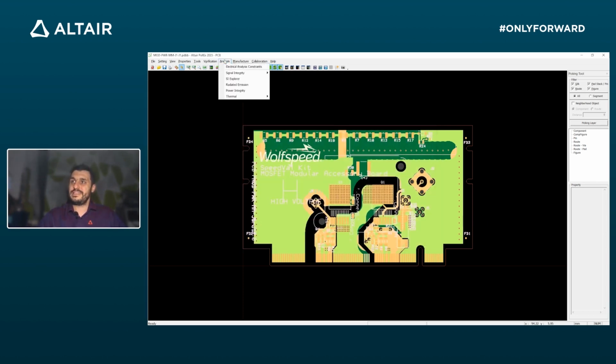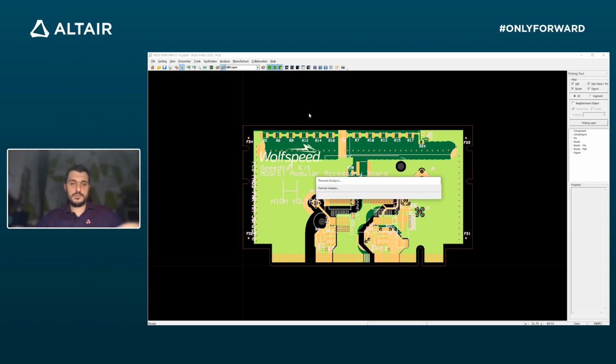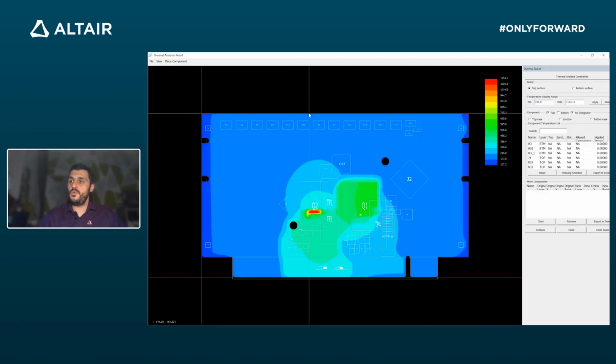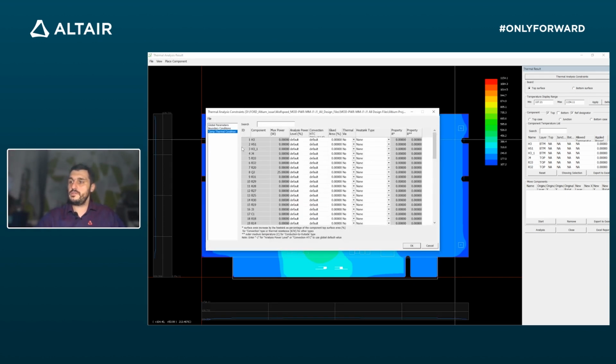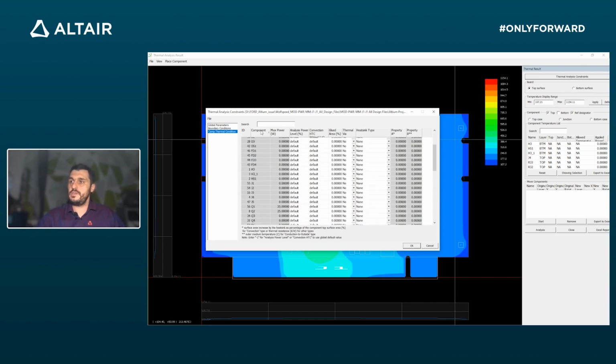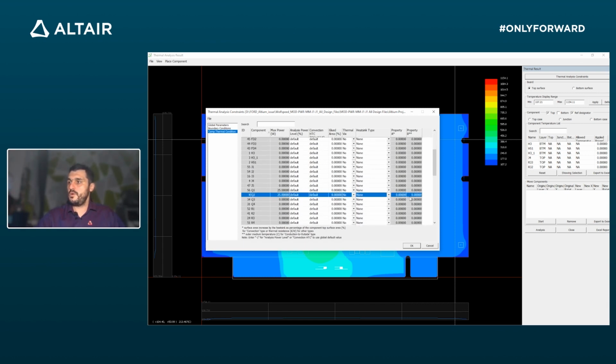Having that set and prepared, we can run a thermal analysis of the PCB board, finding out where the hotspots are and how we can overcome a specific hotspot. For instance, for this Q2 transistor, we can consider putting in a kind of heatsink solution which will conduct heat to the outside with 20 kelvins per watt to 20 Celsius degrees.